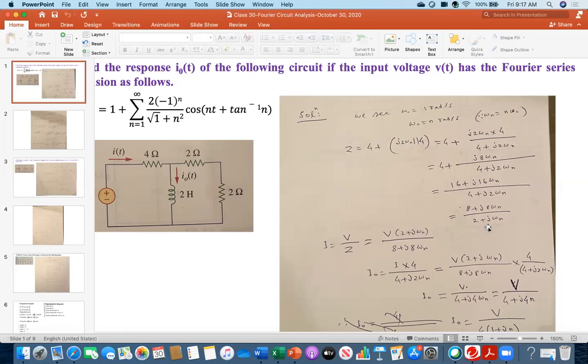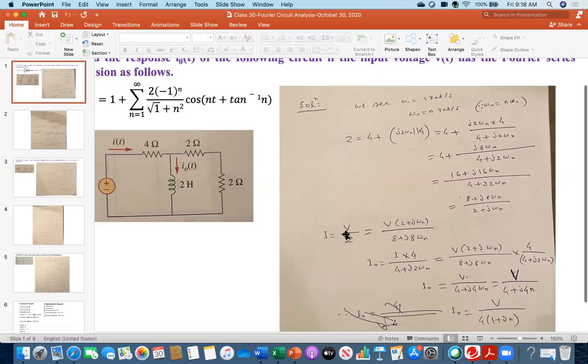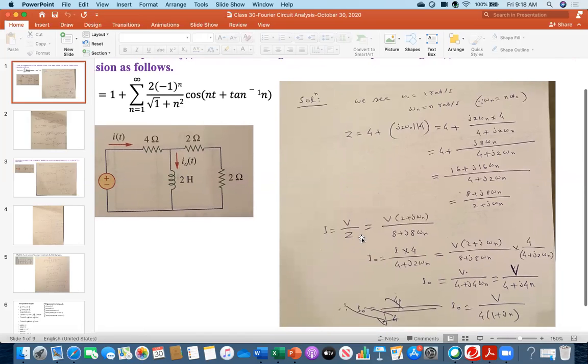I got this one. And once I got this one, this means this is the total J. And then now you come back. So first you find out total current. I am doing it in phasor form, as you can see. That's why I'm using capital I, capital V, capital J. Here those are the time function, time domain. At last we have to convert into time domain, but right now I am applying the phasor domain. So therefore everybody see I is V over J.